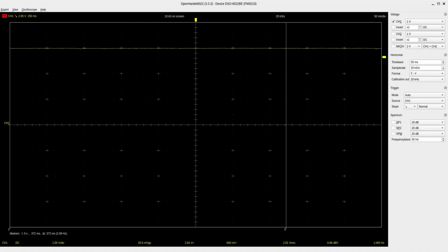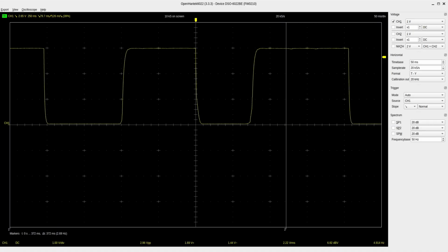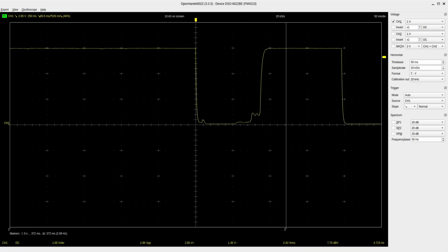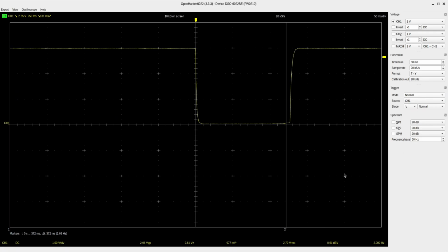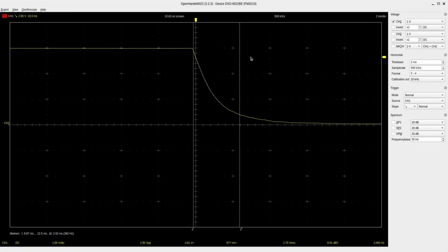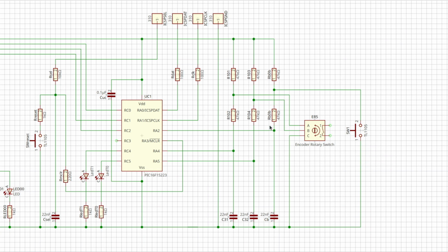And if I tap the button repeatedly, you'll see it go up and down, but you might also be seeing some interesting things happen on that waveform. It's not exactly up and down, there's a bit of a gradual change there. Now if we zoom in and freeze it on one of those button presses, we can take a better look. There, we've captured one of those button presses. And zooming in on this, we can see that it takes about 5 milliseconds for that signal to drop down to 0. And that's due to the resistor and capacitor over here in that circuit, which softens the change.